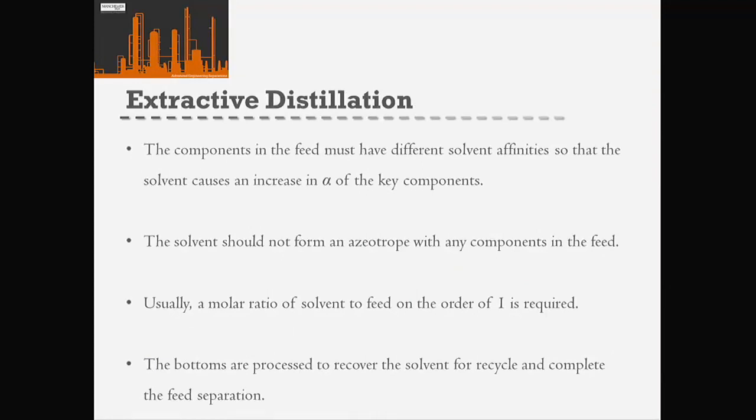So although that's a great option to use and is actually widely used in industry, the problem that we have is that we actually need an azeotrope that moves with pressure. As you saw, it needs to move really in excess of about 5% in terms of composition over a moderate range of pressure, only a few bar.